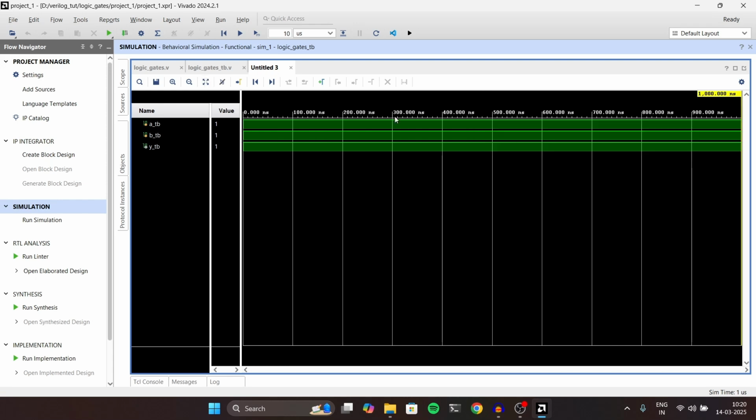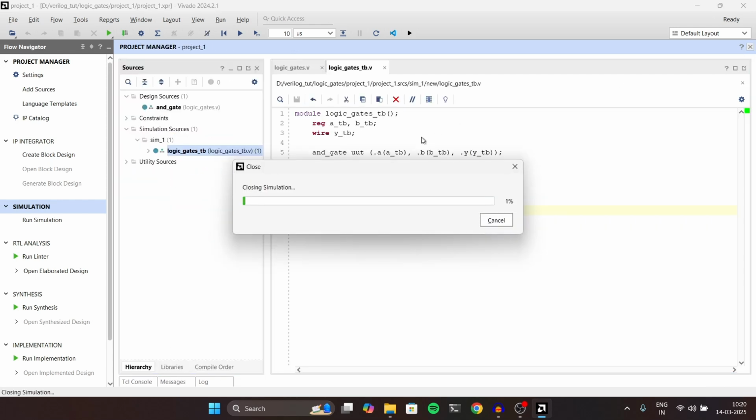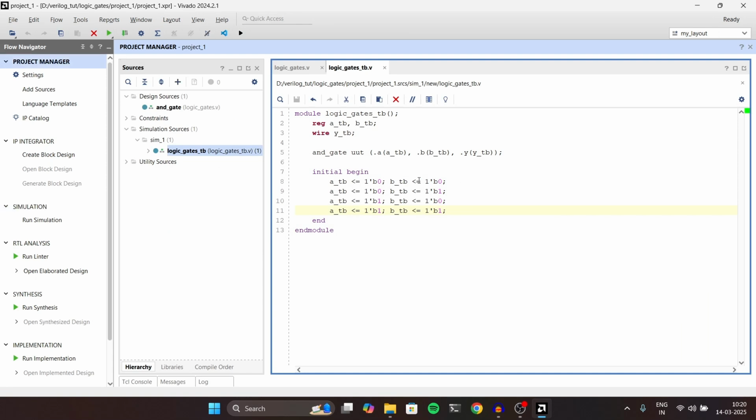So now if I see this, you can see that the values are not starting with 0, 0, but with 1, 1. The only reason that explains this is you didn't define any delay for every case. So it will change from 0, 0 to 0, 1, and 0, 1 to 1, 0, and from 1, 0 to 1, 1 very quickly, and it will stay at this because we defined them as registers basically. These conditions are shifted very quickly, and it will go for the final case.